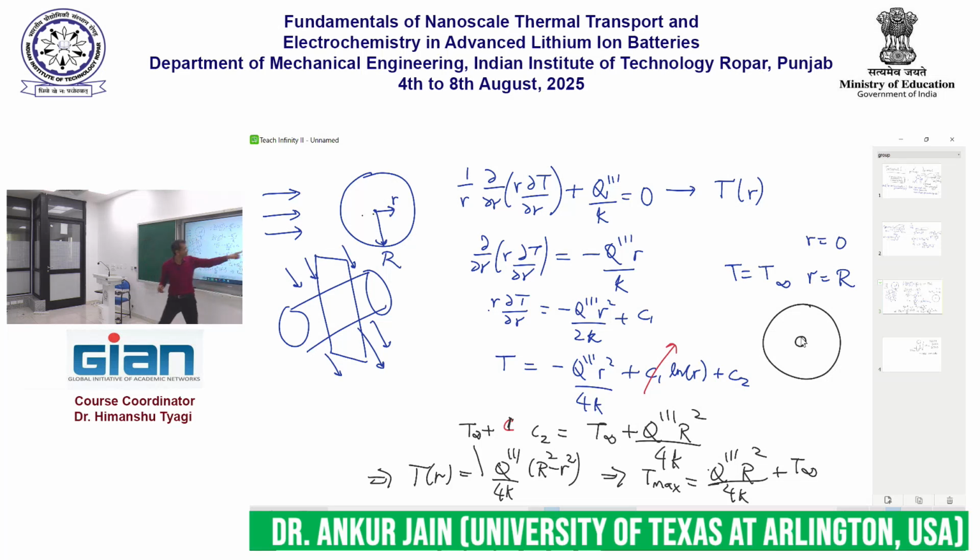And even if this is a very small channel, and even if you don't blow a lot of air, even then it provides us very good heat removal capability. The simple reason why this does not happen in reality is that it makes the manufacturing much more complicated. It is much easier to manufacture a solid cylindrical cell than it is to provide a hole passing through the cell. It messes up a lot of things.